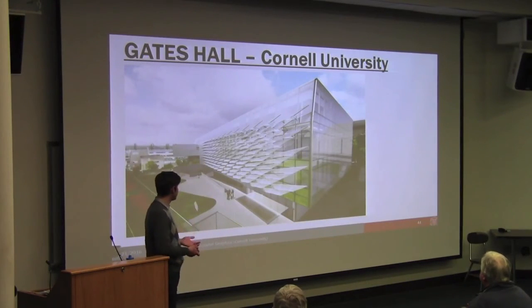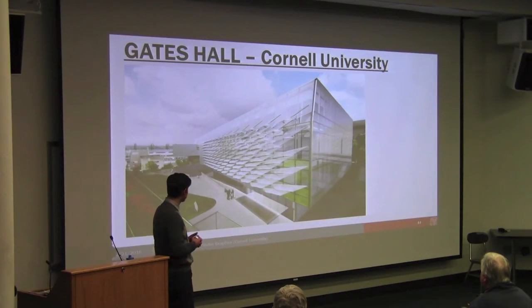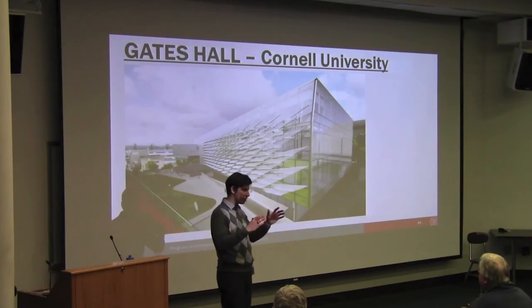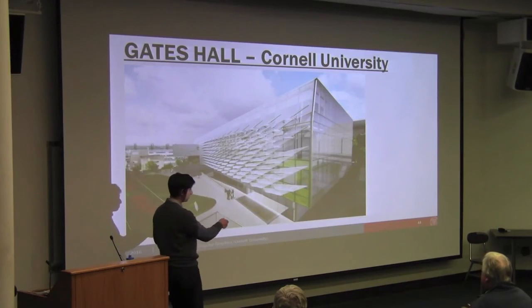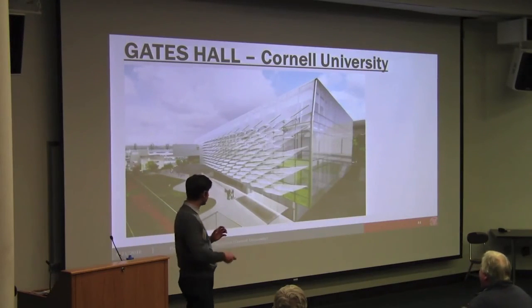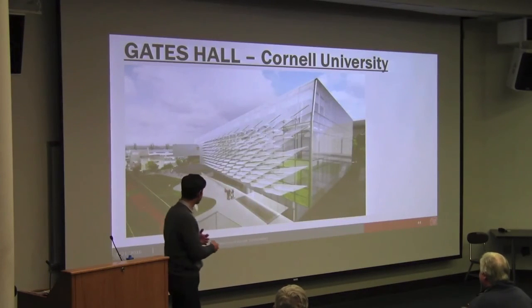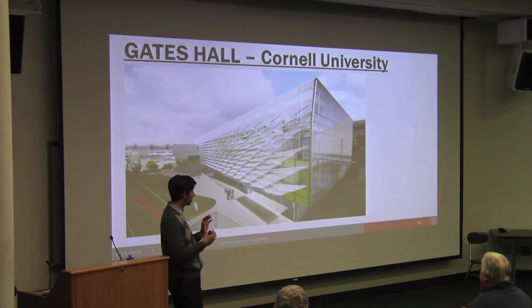Whether you're building a new building, like this is Gates Hall, where they put all these wonderful fins outside of our new Bowers Computer and Information Science building. I asked them when I came here, oh, these fins, they must block the light, and no, they do nothing but make it worse. They actually bounce the light into the building, and it makes it partly unusable. So what we want to do is not just do things that are aesthetically pleasing. We want to make sure these panels are put at an angle or actuated such that they actually block the light.